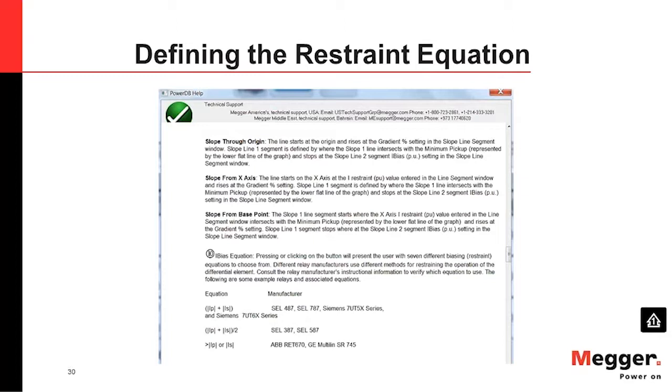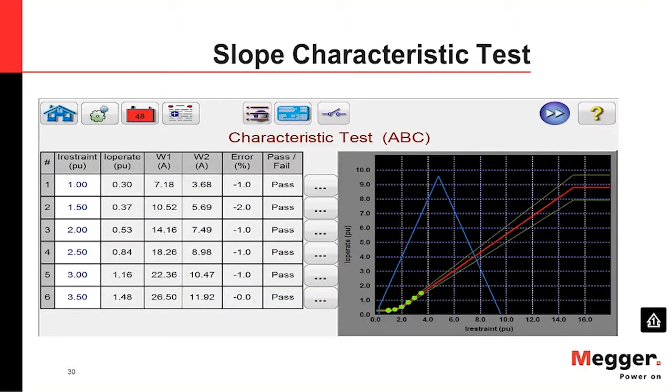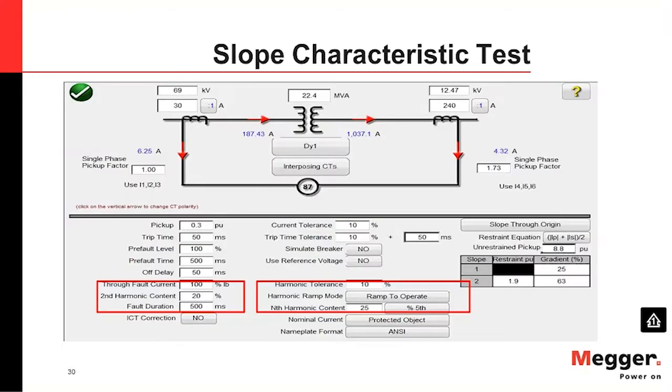After the slope, we will do the harmonic. We can do, of course, the second harmonic, and then we can put 5th or any harmonic. We can choose here any harmonic, but commonly used also the 5th harmonic. So the setting over here is the harmonic setting, which is second harmonic, and the 5th harmonic over here.